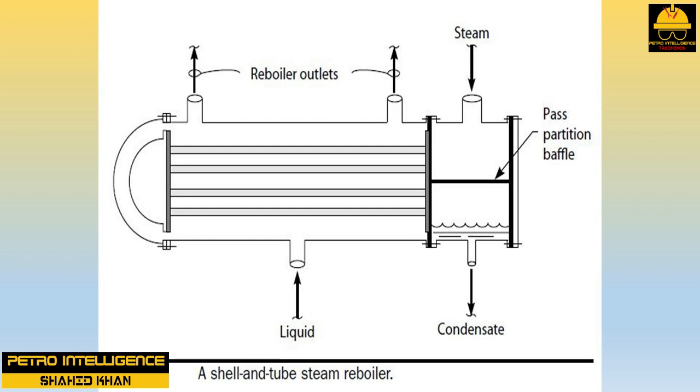If the reboiler is a thermosiphon or natural circulation reboiler, then low process side pressure drop is important. For a horizontal reboiler, it is easiest to obtain a low pressure drop for the fluid being vaporized by placing it on the shell side. The steam enters through the top of the channel head of the reboiler. Any superheat in the steam is quickly lost to the tubes. Superheating steam does very little in increasing heat transfer rates in a reboiler.